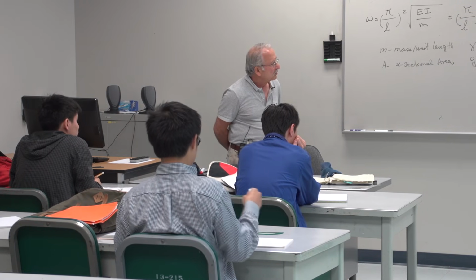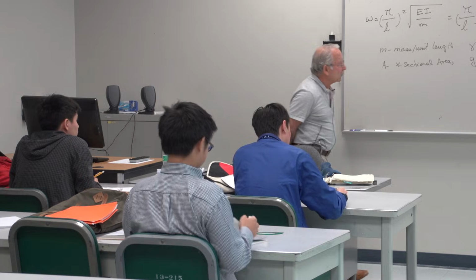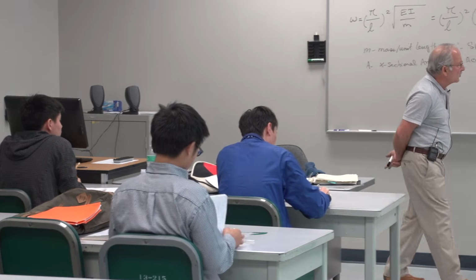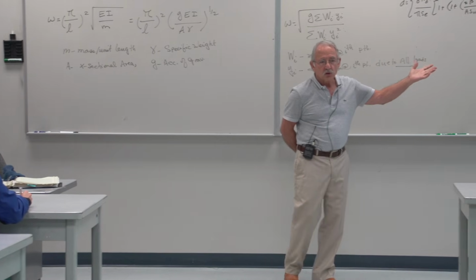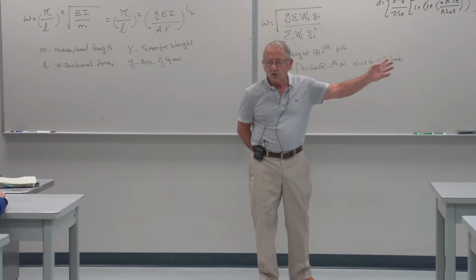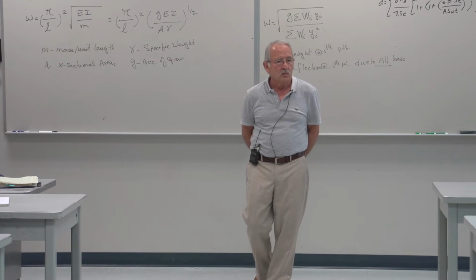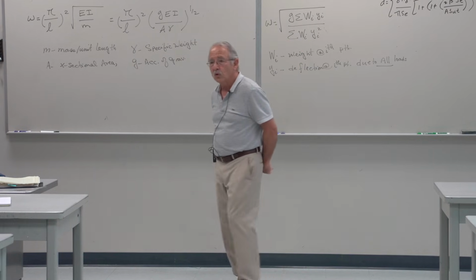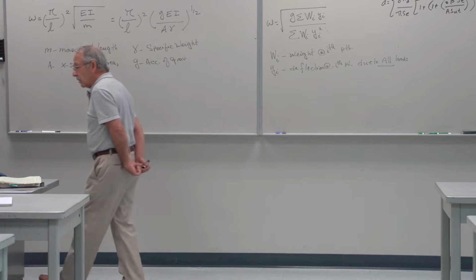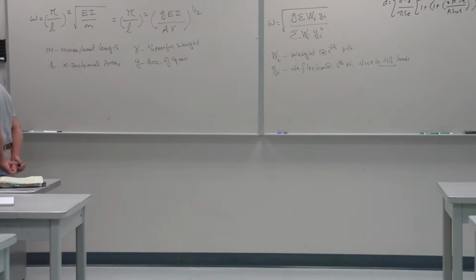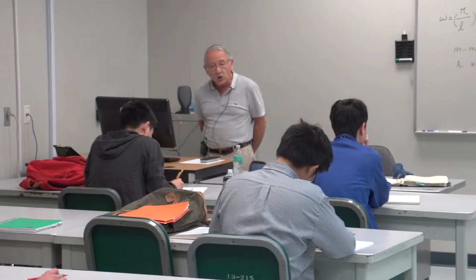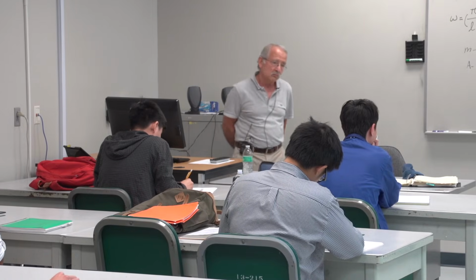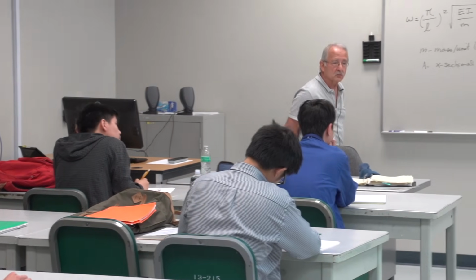Let's see. The questions for the general fatigue problem could include a shaft such as this. And if you're to use these equations, I'll refer you to these equations, and you can use them straight out. Or if you are asked to draw a Goodman line or a Soderberg line, write the equations and actually show how you get the values, then that's kosher as well.